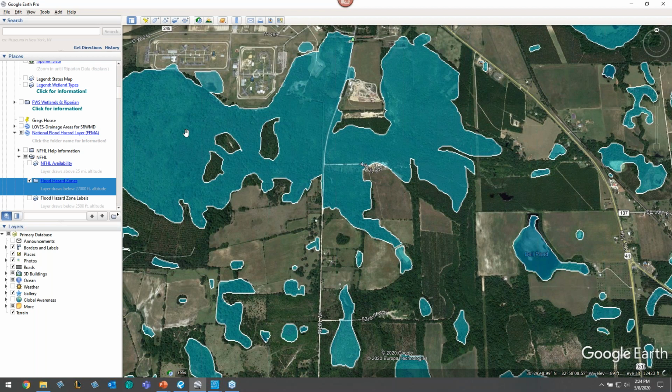For those of you not familiar with this, I hope you're somewhat familiar with it if you're in engineering, but whatever kind of project it is, a site job, a mall, a road, it doesn't matter. Water management requires that you check the floodplain to see if you need to define or create a floodplain compensation pond. It's not a pond that needs water quality or anything like that. It is literally a pond that you're just digging out the earth.